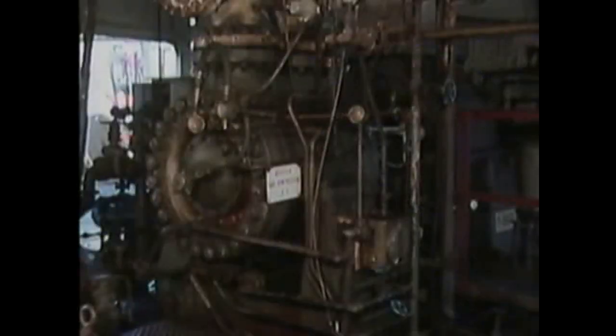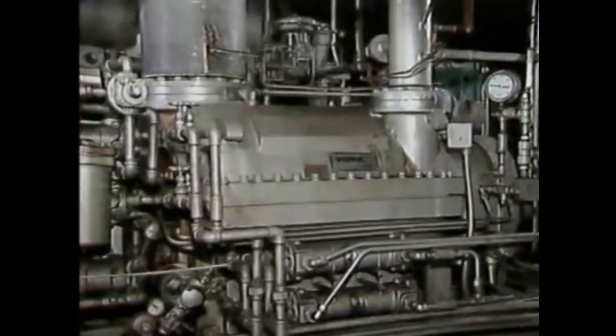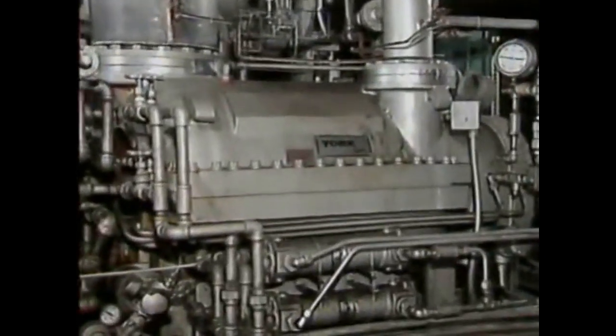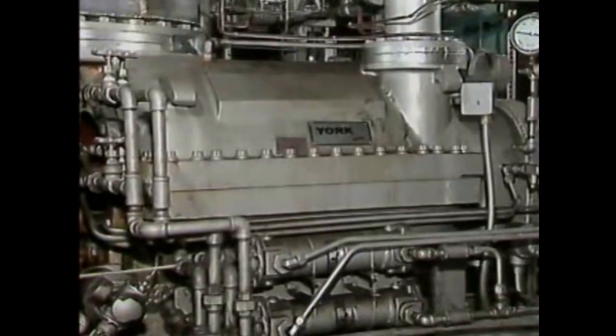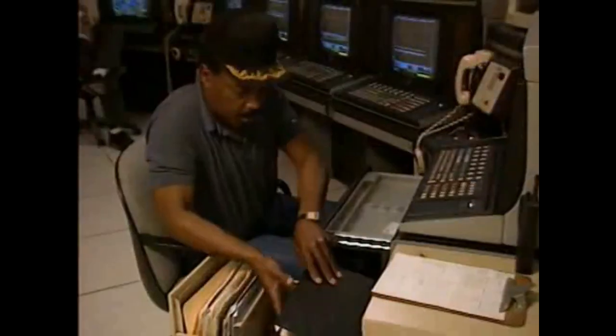As a general rule, it's important not to exceed the ramp rate while a compressor is being brought up to speed. However, in many centrifugal and axial compressors, certain rotational speeds, called critical speeds, cause severe vibration. This vibration is caused by the physical characteristics of the compressor's rotating parts. The vibration can be severe enough to seriously damage a compressor.